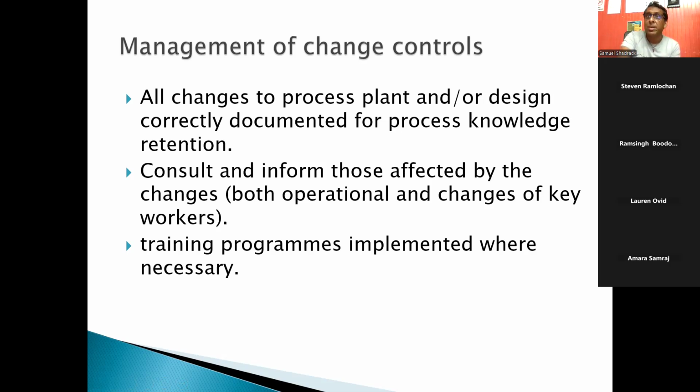You're going to change an alarm, you're going to change a level gauge, you're going to change the flow rate, pump rate, RPMs. So maybe via testing in the machine shop, you realize that the RPM of the pump, which is the revolutions per minute, could give you a better yield if you slow it down a bit and let it run at a normal pace. So instead of running pretty fast, you slow it down to 60 revolutions per minute, which is not bad. Some may go higher, some pumps lower.